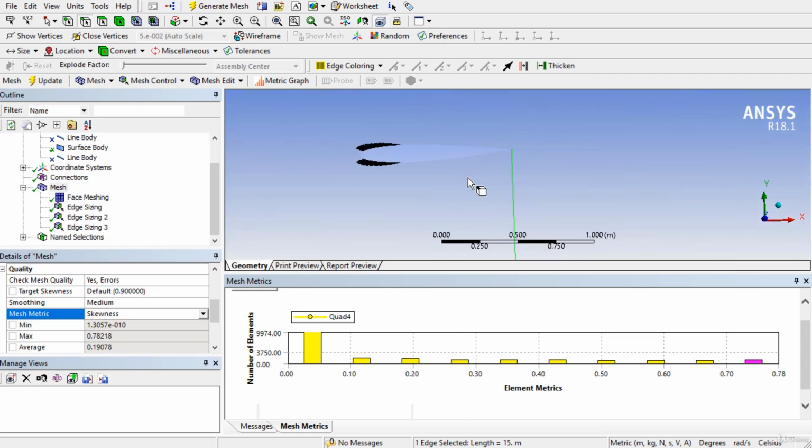And the last option is to use ICEM CFD, because in ICEM CFD these things are very easy to control. We can subdivide the domain into many zones, different parts, with just one click. But in Ansys meshing you have to go back to the DesignModeler to make the changes in the geometry. So ICEM CFD is recommended for high quality meshes and highly accurate results. Anyhow, the next thing is to check the mesh statistics.